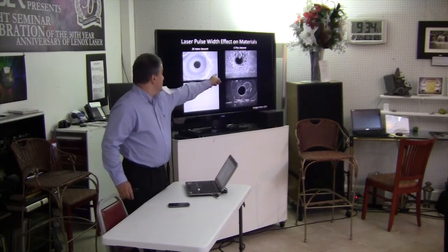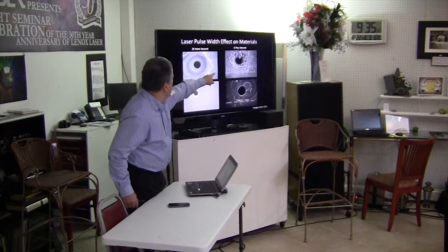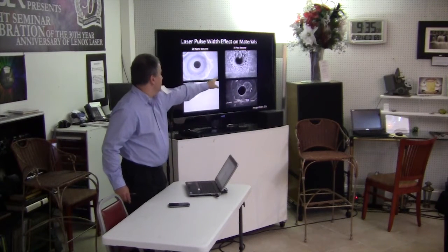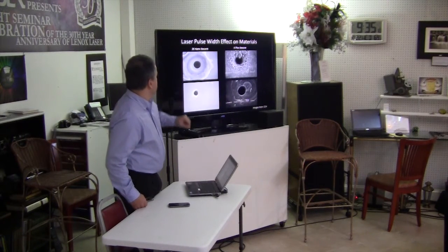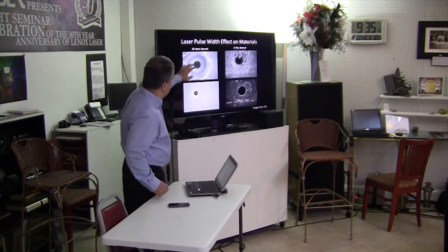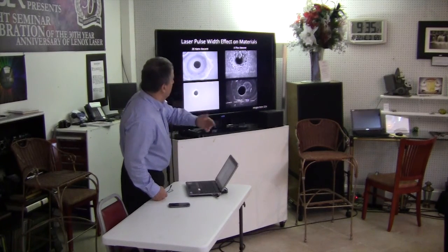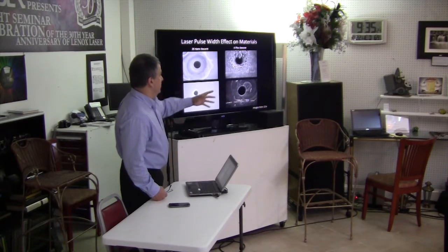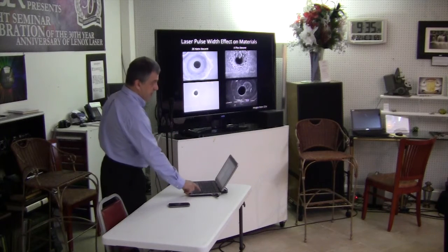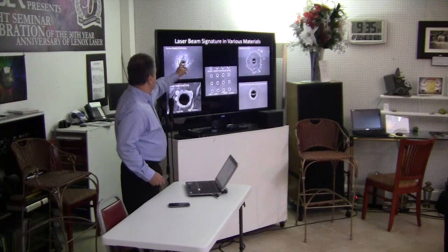This is the pulse width of the laser beams. So that material was done in an alloy, I think that's a Kovar or Inconel, something of those, the top picture with the picosecond laser. So the physics is absolutely different. You see some melting around here, that's a clean hole. You see some other defects, like material was ripped off at the very end of the material, and we're just trying to analyze that and improve the process later. And actually, that was Kovar.